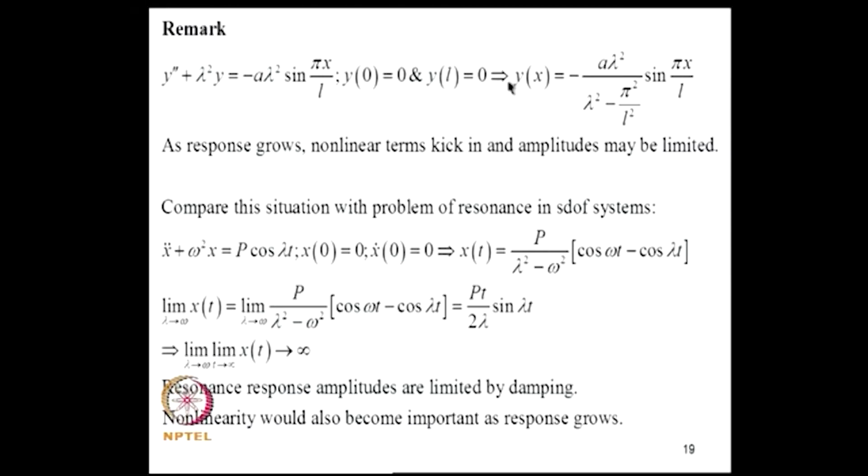Although a linear theory depicts that amplitude becomes unbounded, once other nonlinearities are included, because response amplitudes have become large, the amplitudes may not really tend to infinity. Now, to gain an insight into the behavior, we can compare this situation with the problem of resonance in single degree freedom systems. The governing equation here is y double prime plus lambda square y, excited by a sinusoidal function.